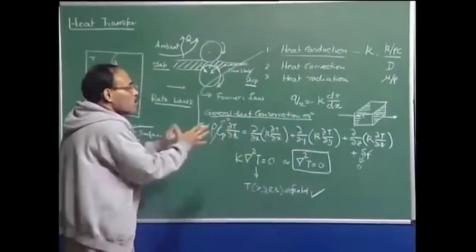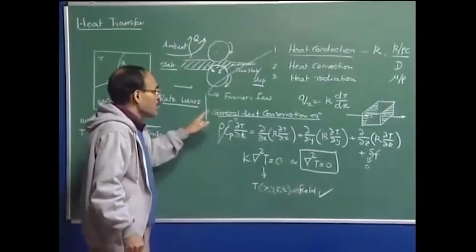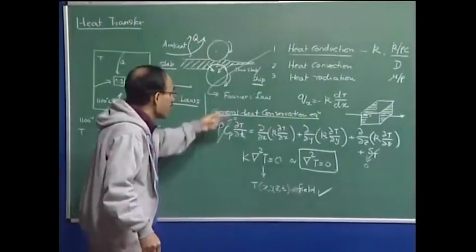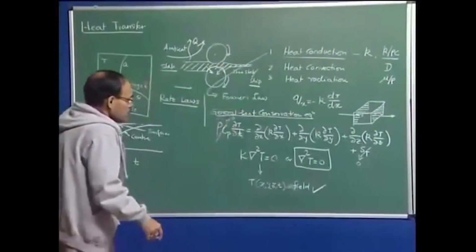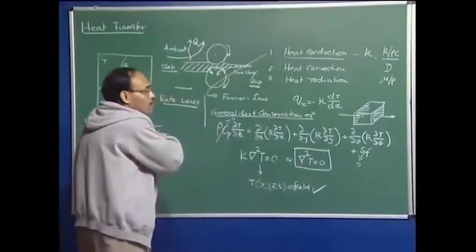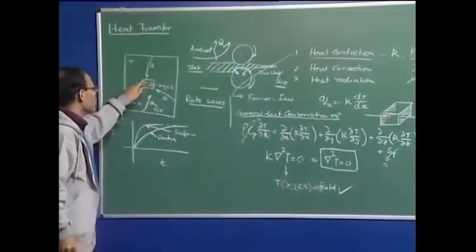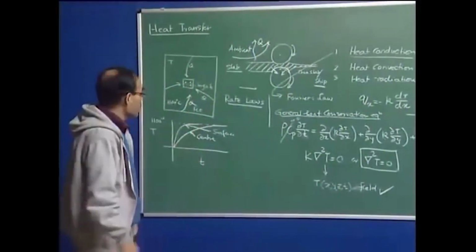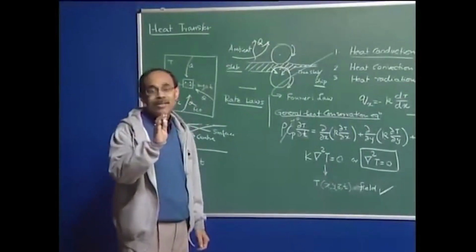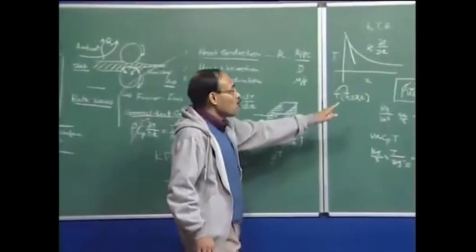While in conduction, as you have seen, there is no fluid flow involved. So, the rate law is the Fourier equation, and we can solve the governing energy equation without any knowledge of fluid flow, because there is no fluid flow within the solid. But before we can address convection, we have to know about the fluid flow.